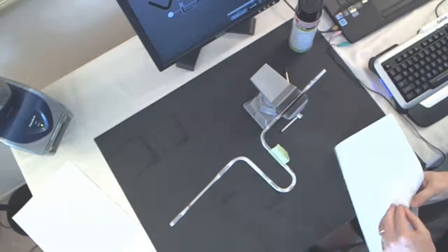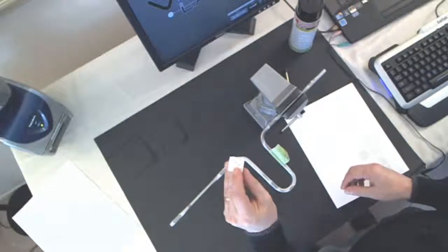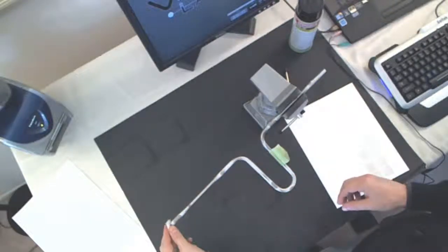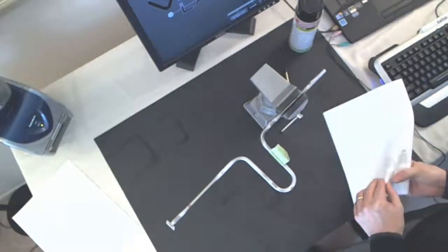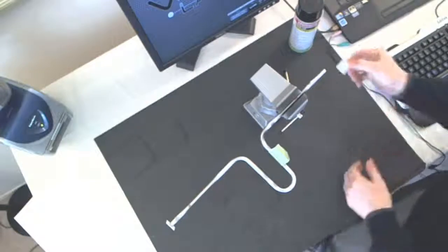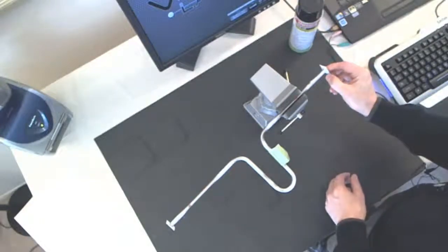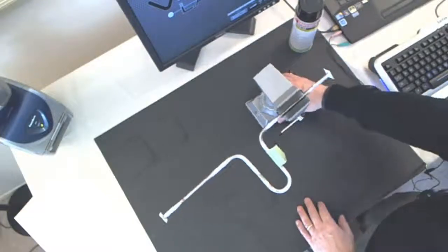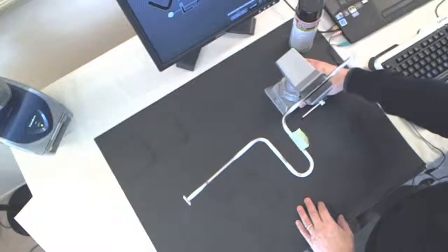To increase accuracy on the end scans, we will apply end targets to each end. These are small white poly labels that are approximately 0.004 of an inch thick. Next, we consider the position of the part for ease of measuring with the FARO arm reach.